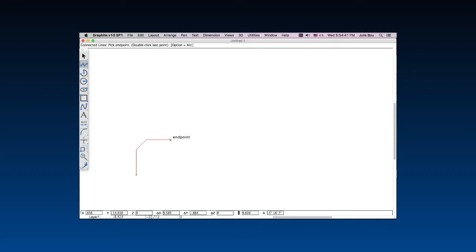Now let's construct a vertical line that ends on the horizontal construction line through the upper point of the first line. Notice that the drafting assistant takes into consideration all the existing geometry and displays relevant information about the cursor position. Move the cursor straight down until intersect appears. Then click to set the point.